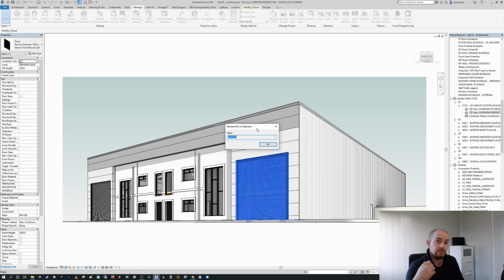For example, you may receive a clash detection report out of Navisworks. That clash detection report will give you an image of the clash, basically, and then it'll give you the two corresponding elements as element IDs. This is a way of quickly identifying within the Revit editing environment what those elements are, particularly in complex models where it's very difficult to navigate and get into the depth of the model for selections.